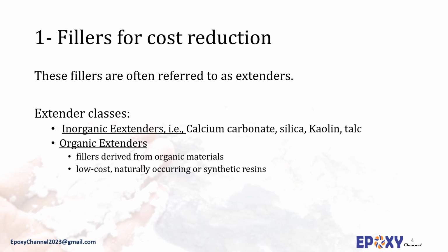Calcium carbonate is the most commonly used extender. Calcium carbonate is available in many different particle sizes and in various grades. To improve dispersion in certain resins, the filler is often coated with calcium stearate or stearic acid. Silica is also often used as an extender in adhesive formulations.